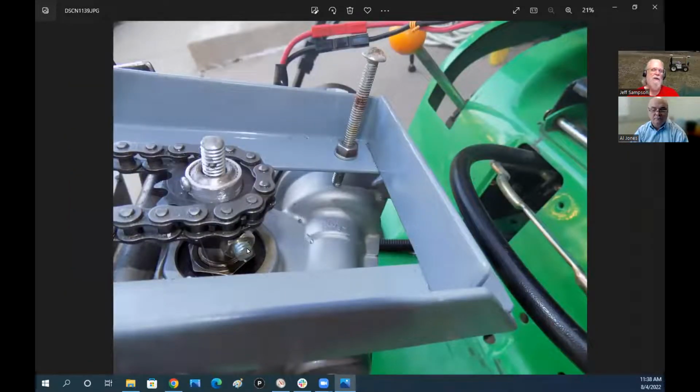Here's another shot of the motor. This is the shaft coming out of this power steering motor right here, and here's that 1/4 bolt that bolts this onto the shaft. Up here I stuck in what is probably originally a bolt or a piece of threaded rod, and then I drilled and tapped into that bolt. So this gives me a 1/4 inch shaft coming off the end of my steering motor, so I can put a pot.